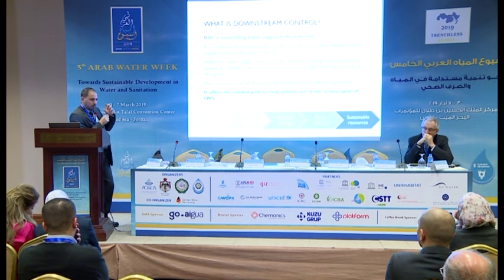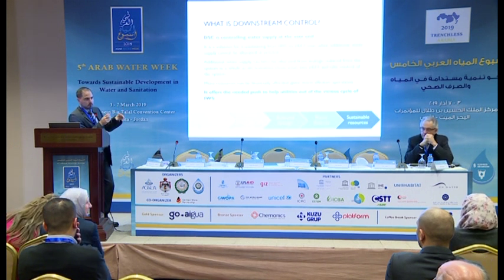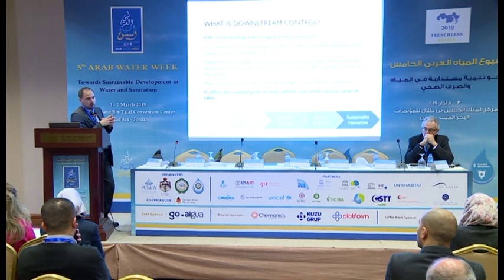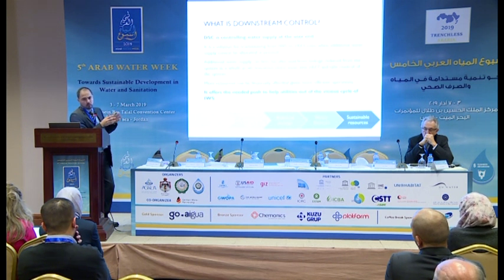Is we try to put at the end user, which is the house connection. The house connection is before the meters, to put a shut-off valve that we can control. And we can close as the rational supply we want, usually like 24 hours, 48 hours. After finishing, we close it, but we keep the water in the network.